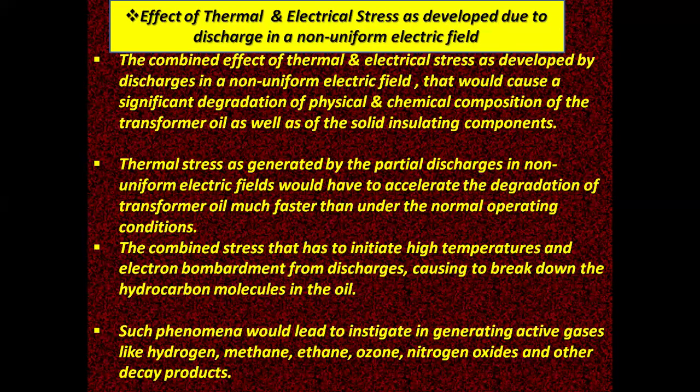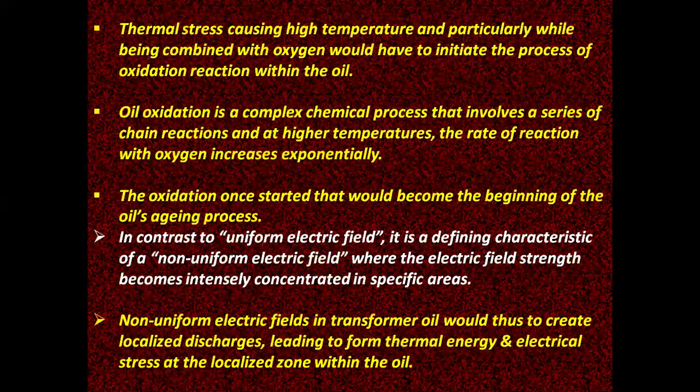Such phenomena would lead to the generation of active gases like hydrogen, methane, ethane, ozone, nitrogen oxides, and other decay products. Thermal stress causing high temperature, particularly when combined with oxygen, would initiate the process of oxidation reaction within the oil.